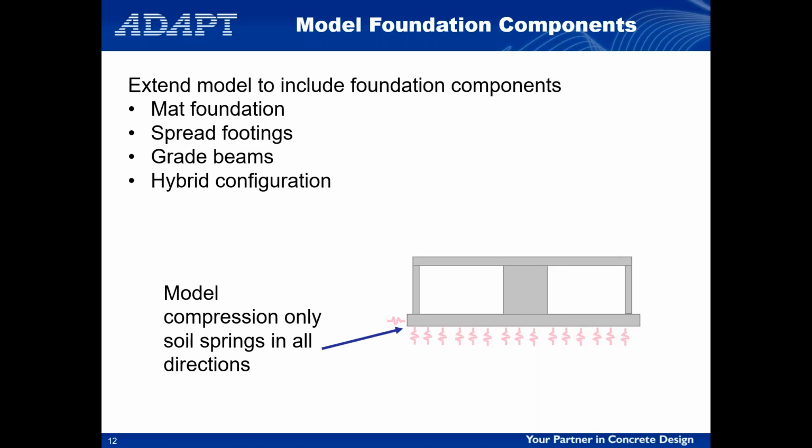So you're kind of stuck with this challenge of, even if I'm using another finite element program to do the PT design, now I've got to take all of those forces, the hyperstatic forces, the redistributed dead loads, live loads, and bring all of those back through the columns and foundations.